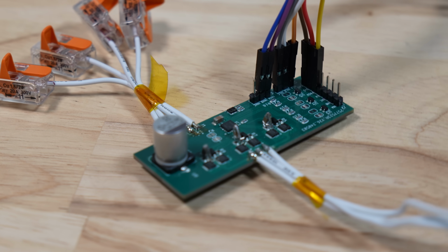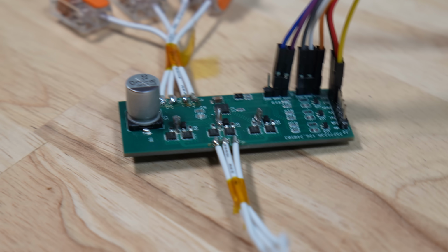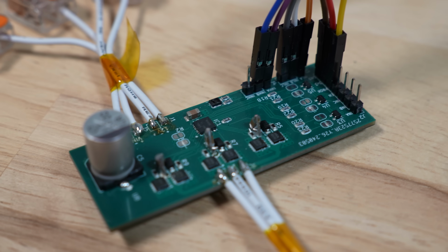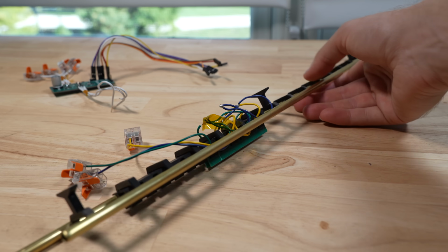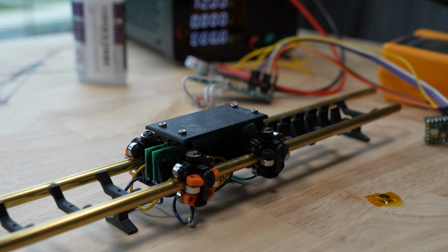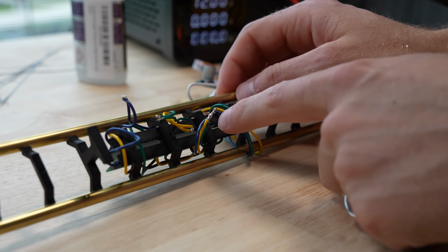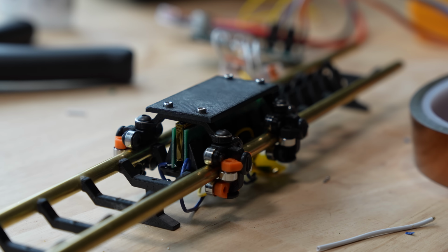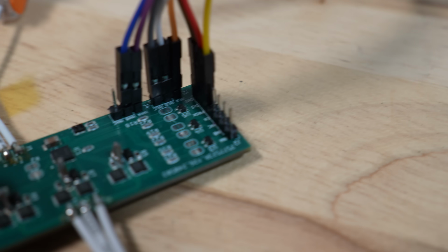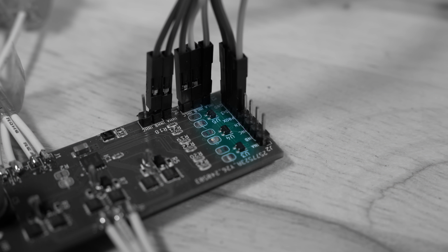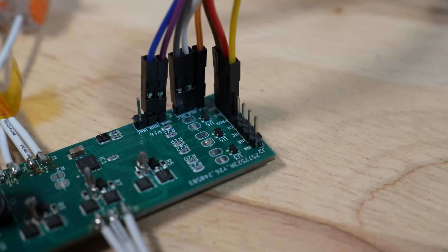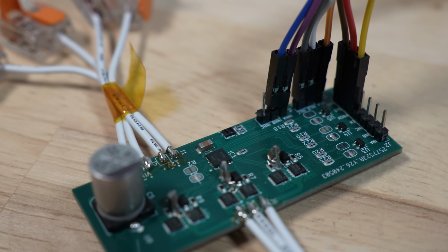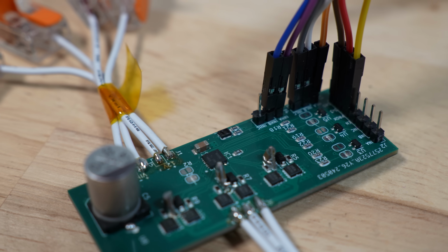This breakout board I made will let me test all the features of the launch coils without committing to a final form factor just yet. This meant I had to solder a lot of connections, and after initially messing up the polarity of half the coils, I got it working. Now in addition to coil control, I also prototyped the AND gate blocks, which I'll use to enable and disable sections of coils, as well as this IR proximity sensor to keep track of the train position in real time. I then proceeded to test neither of these because, well, I don't make mistakes, so why bother, right?